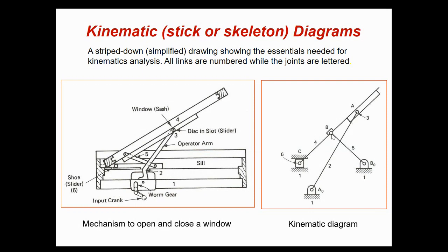Okay, so here you have a revolute joint between the fifth link and fourth link, but you don't have a revolute joint between this part, which I'm showing now, and that part. This part is like a welding, you might say.